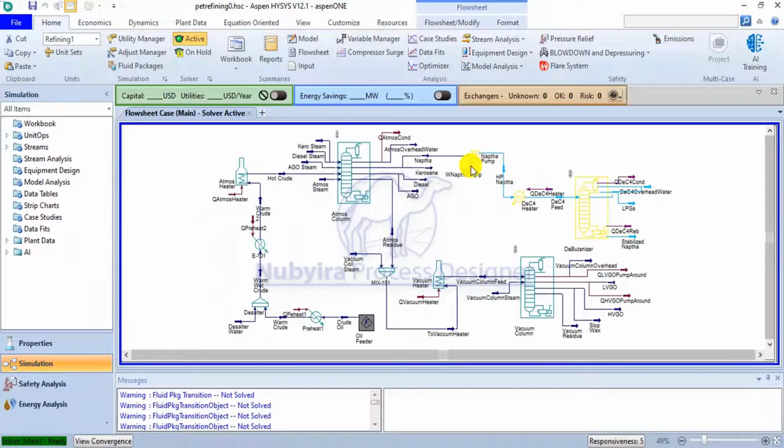I should discuss the meaning of the Debutanizer. From the name, it implies that the Debutanizer is just to remove the C4 content or lighter, that is butane or lighter. It's mostly to remove it because Naphtha is mostly used to blend PMS, that is premium motor spirit, petrol, sorry.